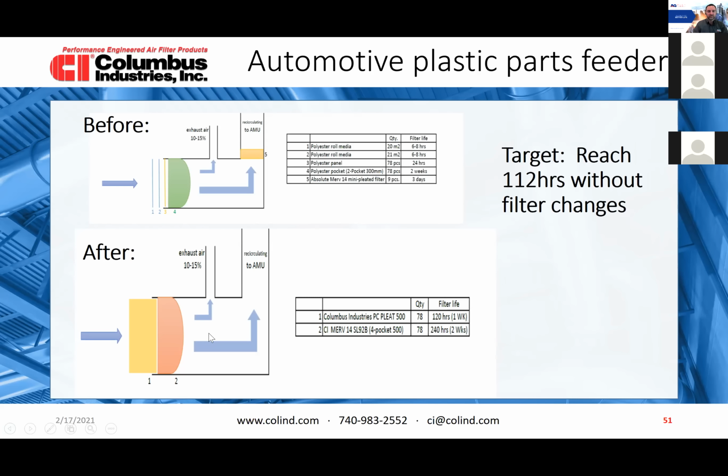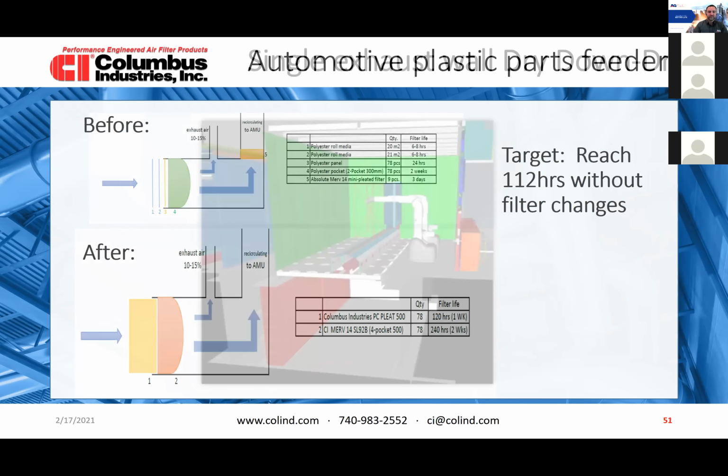So now in this situation versus this, the stuff that's here is a MERV 14 filtration. This pocket is MERV 14. It's not like the other one where it was, I think, MERV 8 or MERV 9. This is 14. It's as efficient as this here. So anything that's out here is pure, it's clean. If it's good enough to come back to here, it is clean. And of course, the pre-filters, the panels.